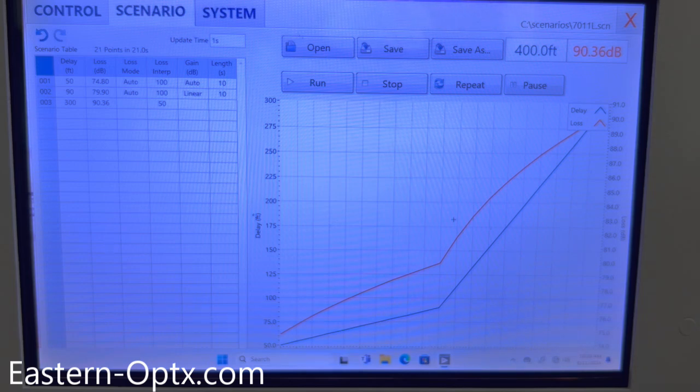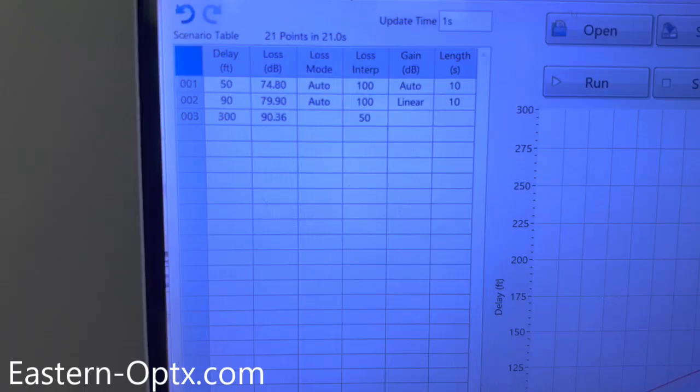Scenarios can be triggered manually or with a remote command. Using the remote command, the scenario can be coordinated with other test equipment and with the reported telemetry from the altimeter. The results, including the timing of the scenario, can be stored and reviewed against the altimeter telemetry. Details of the scenario are displayed in the scenario table. A preloaded scenario may be edited directly using a keyboard entry, or the table can be modified offline and then reloaded.